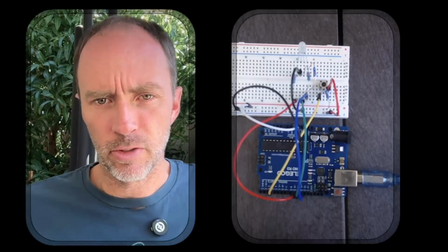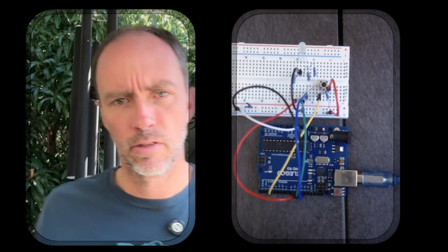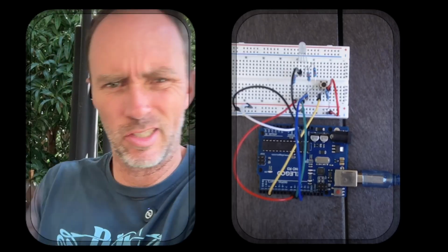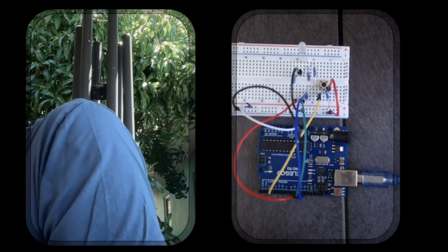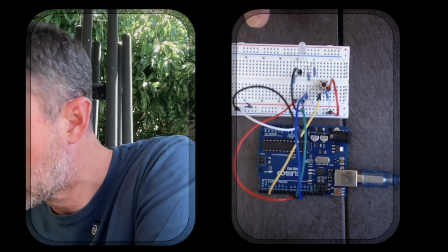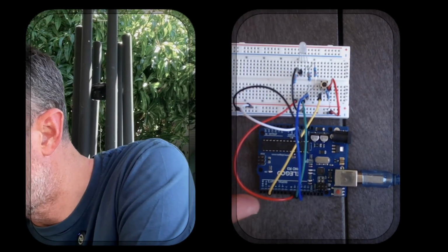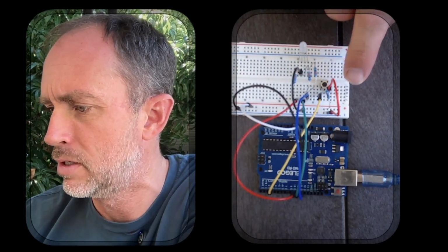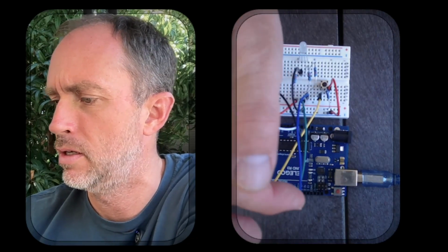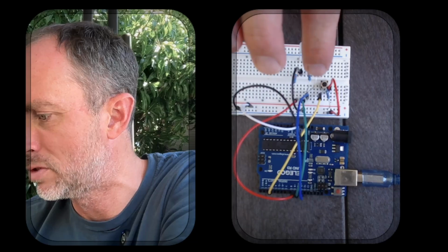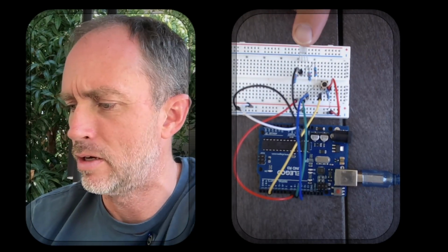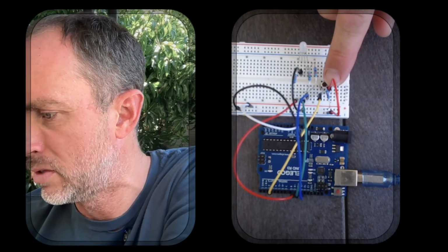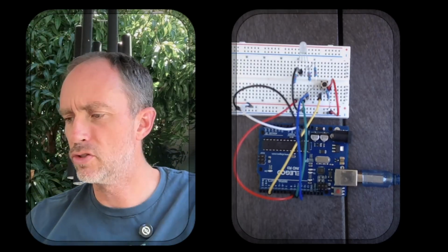All right, so here we've got our embedded system set up. Under closer examination, you'll see that pin 3 over here is hooked up to this button over there. And then pins 9, 10, and 11 are all hooked up to these resistors, going to this little LED. And then we've got power coming in over here. We've got the 3 resistors there, and then we've got our button that goes there. So that's the setup of our board.